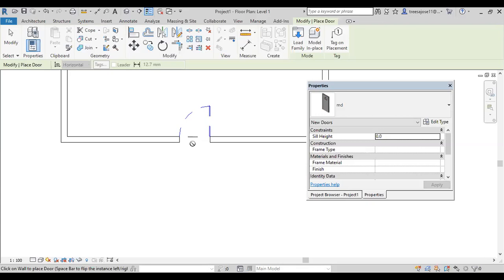Okay, in the case of BIM, actually, while you have to create something, normally your structures may be typical with some parametric changes and all. Better you create a family for that. Then whatever the application may be, you can change. If you are dealing with a lot of projects, definitely you know that in American standards or in UK projects, the structure of the door is different. Then you open the metric door and make the changes with respect to that one. Then make the changes and add it. That is the procedure.